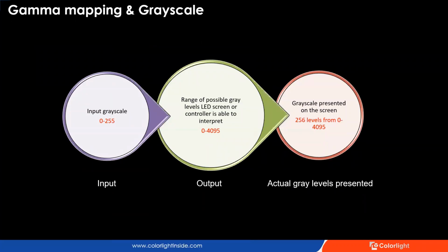Depending on the type of driver IC, there are different gray levels we can set up in LEDVISION software, such as 4096, 16384, 65536. It does not mean an image displayed on the screen will have that many gray levels. Video input grayscale determines the maximum number of gray levels that can be represented in the image on the screen.